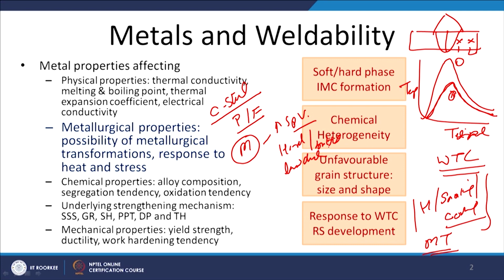So, at the microstructural level it develops residual compressive stress, because wherever the metallurgical transformation from a completely soft phase to hard phases takes place with an increase of specific volume, it leads to the development of residual compressive stress, but the region all around that will be under tension.